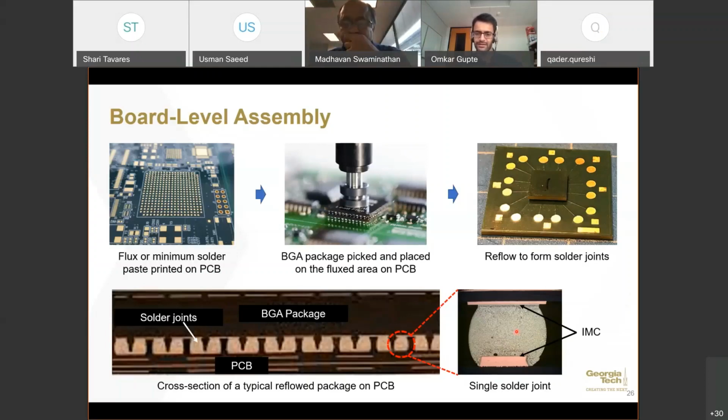So this joint has gone through two bonding processes, two times? Yes, exactly. The first is when the solder ball is attached to the package, and the second is when the package is attached to the board itself. So in this case, should the second bonding process be at a lower temperature than the first one, or at the same?